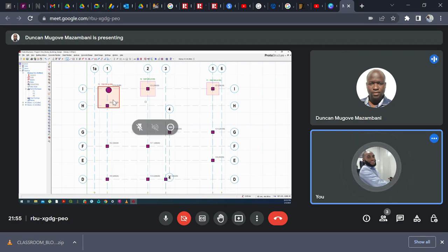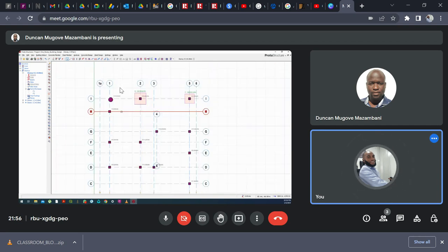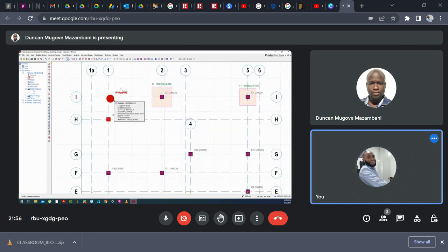Right now, that place where I showed you that if you take off the MX and MY, just now let me delete that combined footing. Just delete the footing. Let me show you how we got that value. Delete that first, then click on that column again, and then separate them from a combined column. Click on it, right click, and then say remove combine. Click on that.